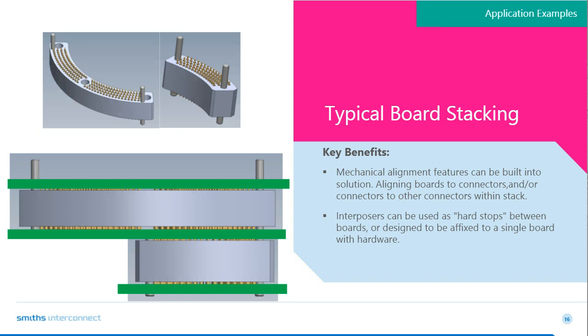This first one shows how you can customize the layout of a pin array to meet your specific profiles and maximize your available space in your system. A typical COTS connector is going to be 4 by 80 contacts, rectangular. With spring probe interposers and the way that we utilize them, you're allowed to develop or design any sort of feature that you need. For instance, if you're using a circular board, you can make a connector that will match the profile or the outside diameter of that actual board.